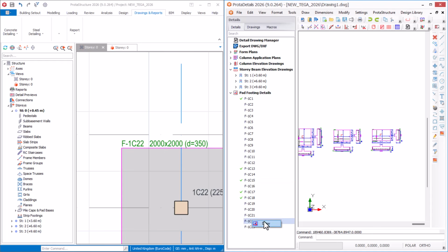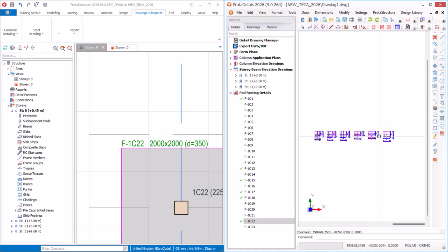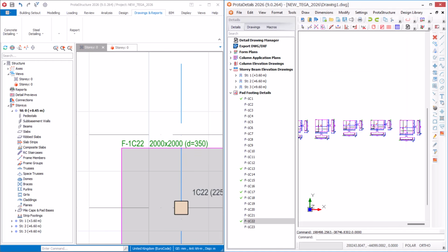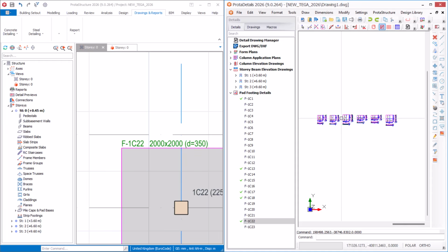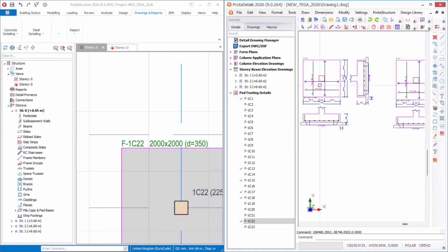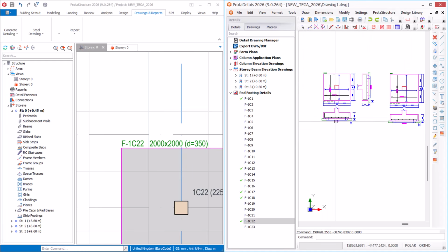So now instead of pasting all the footings and getting confused later, I just paste each of them from different groups. In this case we have type 1, type 2, type 3, type 4, type 5, type 6. So we have only 6 footing types. When we are doing our structural detailing, we are only going to detail 6 footing types and then put the number of each of the sizes under it. Okay, that's fine. So in this case, I will now maximize back this one.